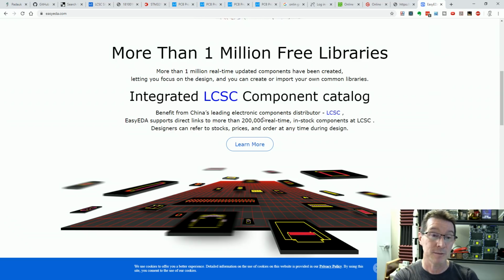If you wanted to promote these Padauk micros, so people just buy the ready-made programmer board, with the firmware already programmed, instead of dicking around with multiple videos, as you're going to see in this series, with all the little traps involved in not only hand building the board, which takes hours to build up. Then the microcontroller's blank, so you've got to program that using DFU, and there's a few traps for young players in setting that up, as you'll see in the coming videos.